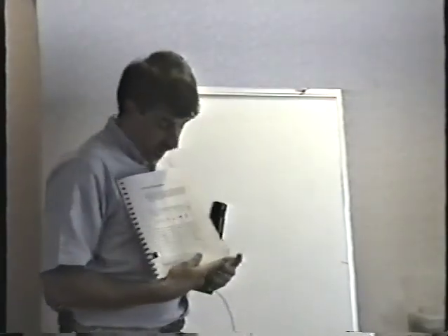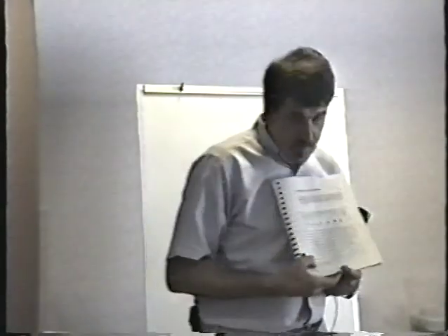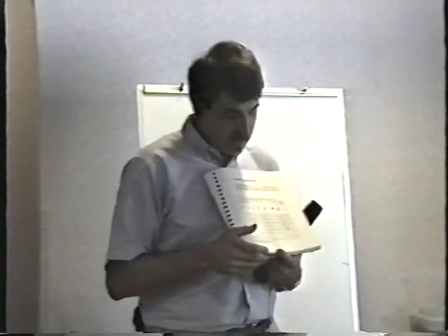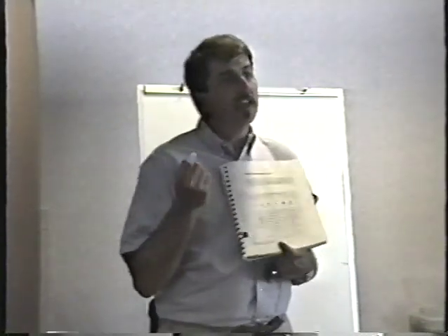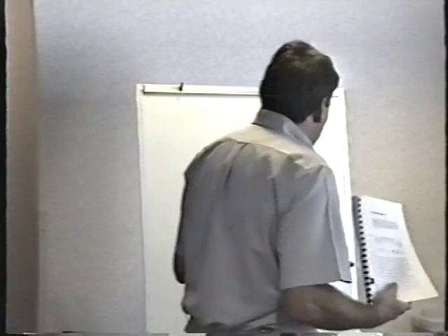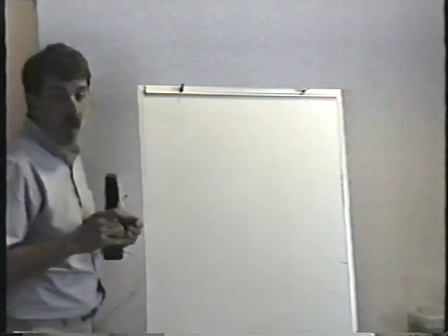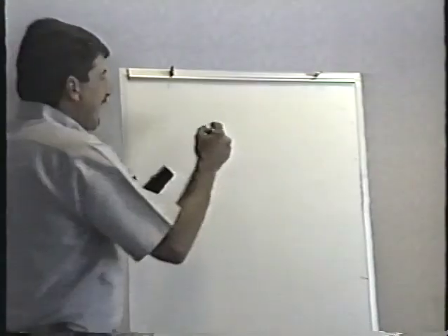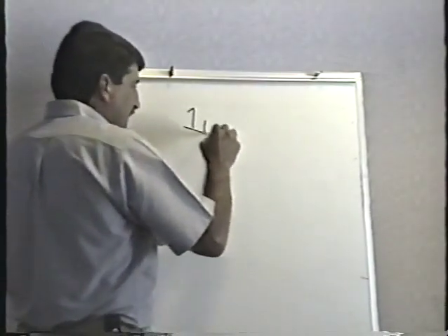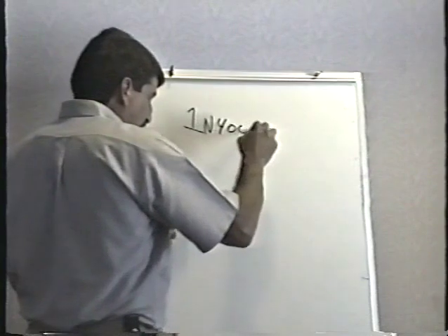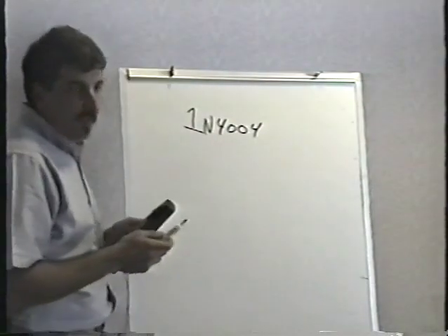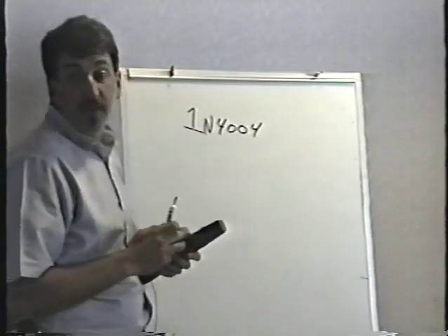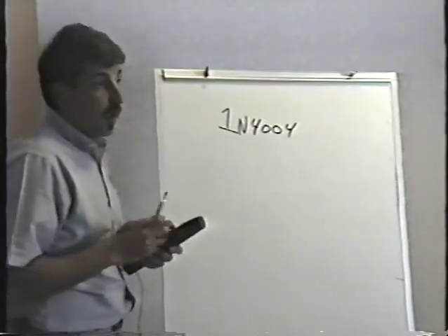If you look at page R5, we see all these different rectifiers, diodes, rectifiers. Let's take a look at the two diodes that you have. Let's take a look at the small one first. What is the part number on the smaller of the two diodes? 1N4004. Right. It's a 1 and not an I. 1N4004. A very common part. I think almost everybody is familiar with the part. We use it all over the place in games.